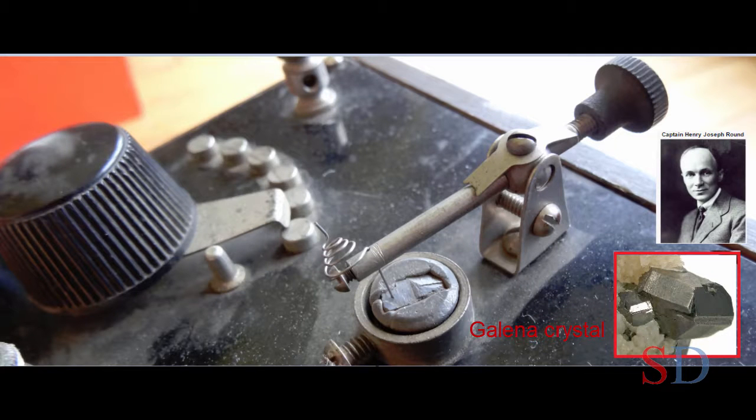The first radios used at the turn of the century were simple induction coil radios: no batteries, no electric current, no electron tubes. They were just two simple coils, and they had to control the frequency of the radio signal itself, so they used a silicon carbide crystal, and on top a small wire where you would locate a sweet spot. This was called a cat whisker diode, and it's one of the first diodes that was not an electronic tube design or integrated circuit.